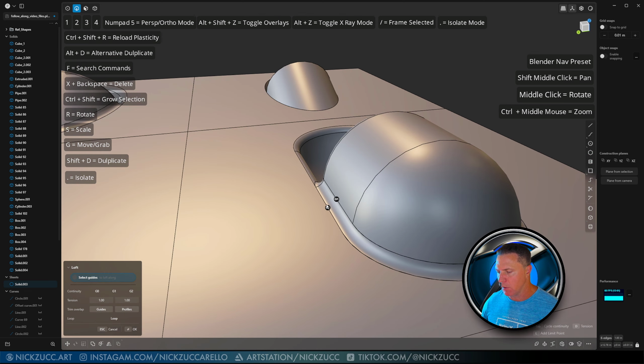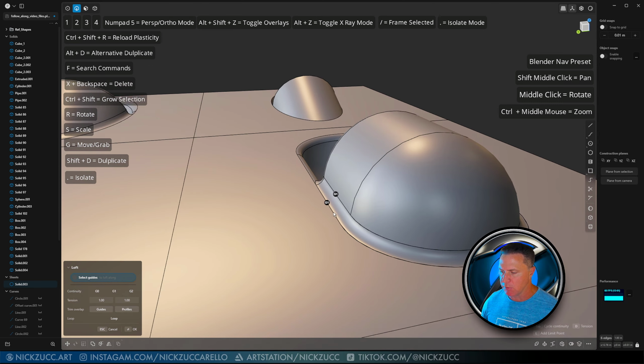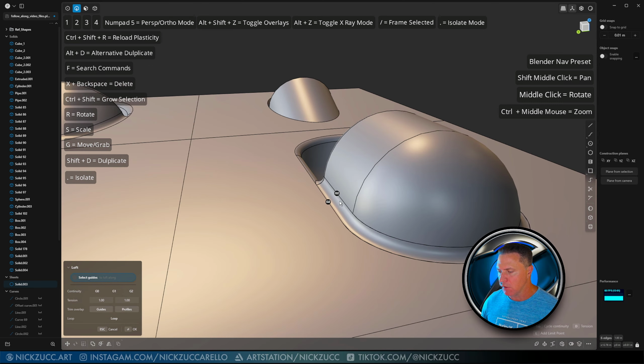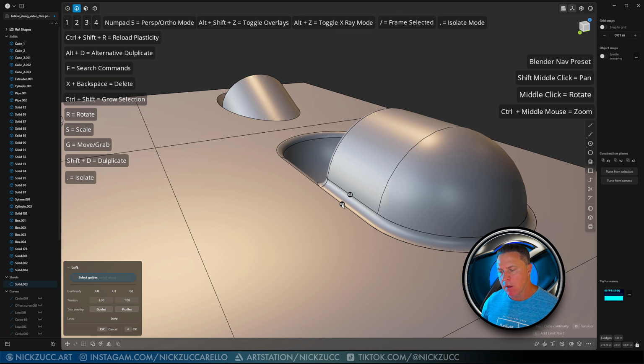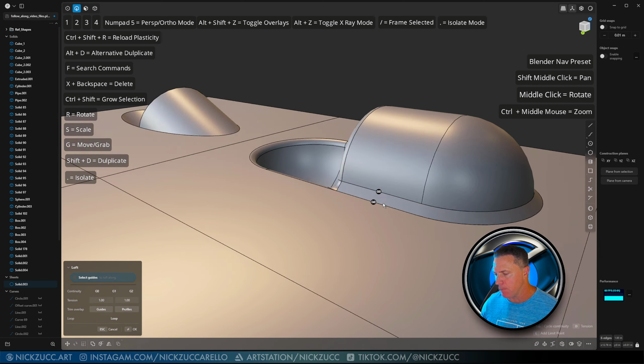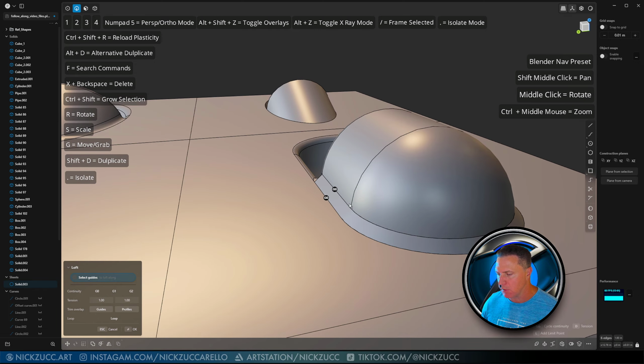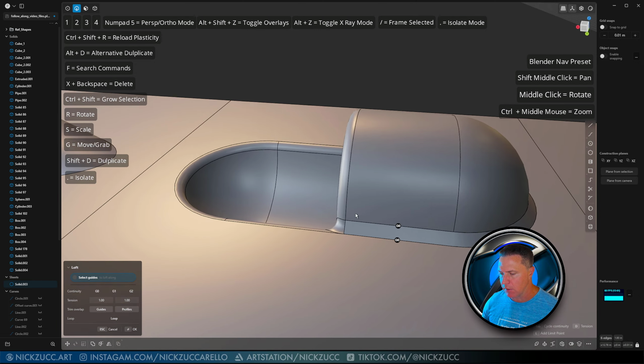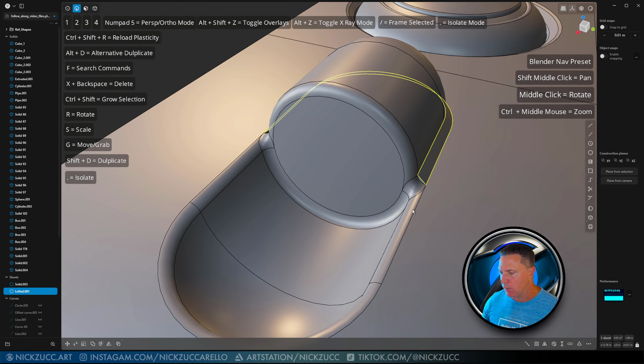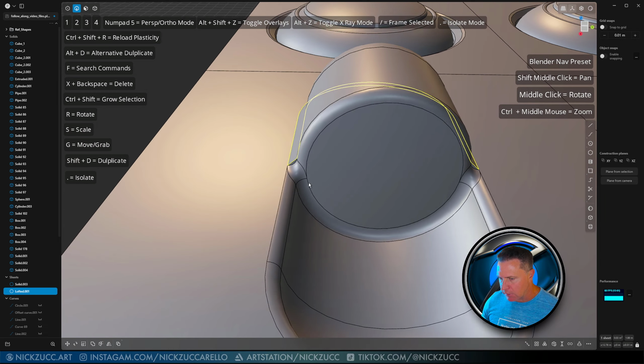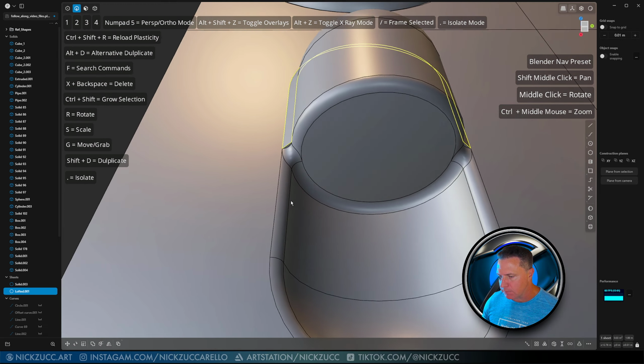If I do G1 on this, smooth transitions between both. And if I do G2, that's even more curvature. So a lot of times the G2 actually fails, so your best bet is either G0 or G1 with this. But if you wanted the chamfer instead of fillet look, you would use G0 on this, right? So I could come back through, and you can see it's not connected to that piece anymore, which is fine.